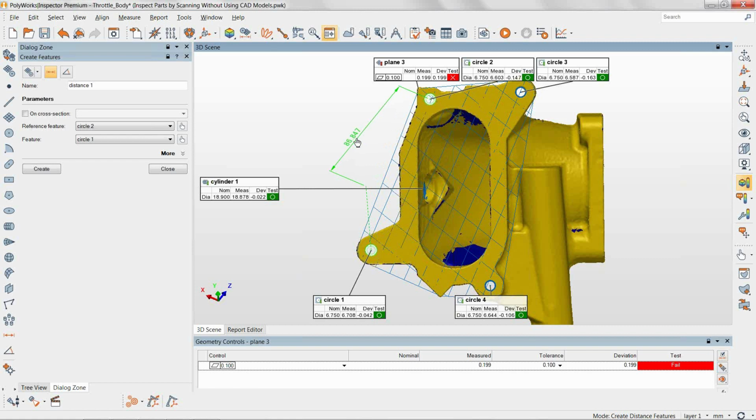And typically when we work with CAD, we might be accustomed to having a coordinate system that's relatable back to the part, perhaps representing how the part is machined, or perhaps representing how the part's positioned in some sort of assembly. In this case, because I don't have a CAD, the coordinate system that we have came from the device I scanned this part. So it's not a very relatable coordinate system back to our part.